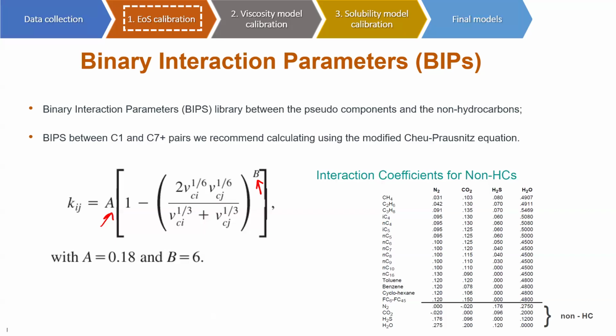For the hydrocarbon components, the BIPs are usually controlled by the thermodynamic properties of the equation of state, right? So the mixture is calculated by the equation of state. But whereas the non-hydrocarbon components such as nitrogen, CO2, H2S, and water, how would these be controlled by the equation of state? Is there gaseous diffusion, or how are they going to be mixed together?